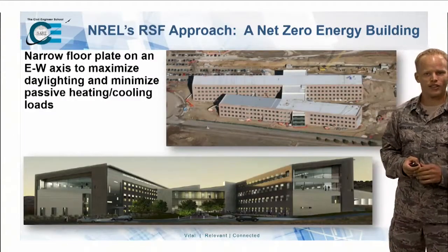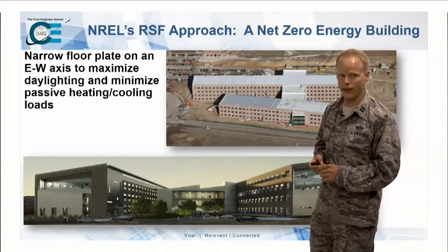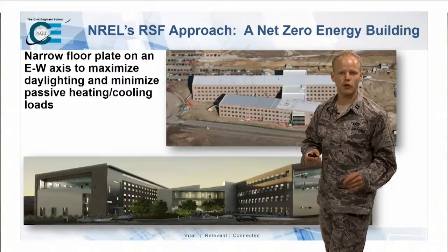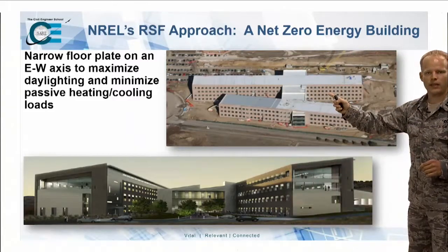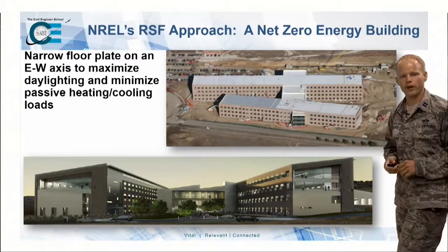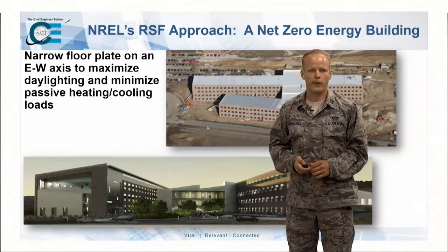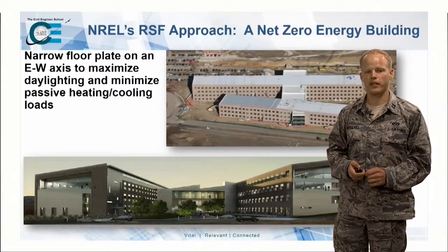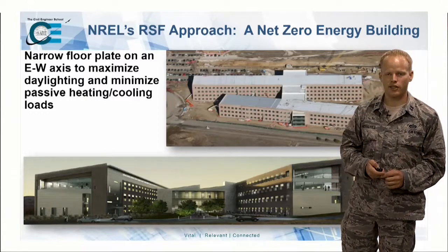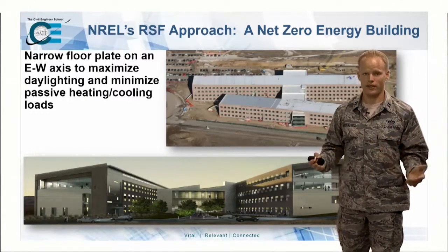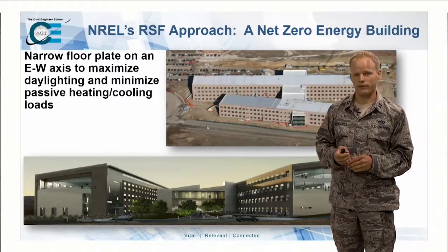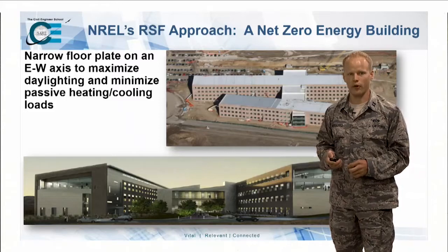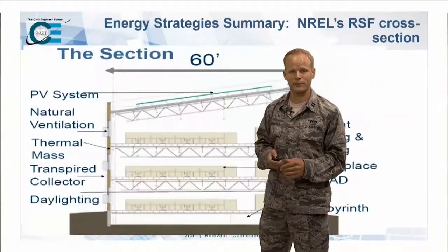So this is the Net Zero Energy building. They are very proud of it. The National Renewable Energy Laboratory. I sat somewhere right about here. Had a window cubicle. But you can see they maximize their east-west orientation. They get a lot of daylighting in from the southern face and then minimize that east-west. In Colorado, you can imagine it has a very high sun. The sun will really heat up the building. Then they also slap PV all over it, photovoltaic cells.